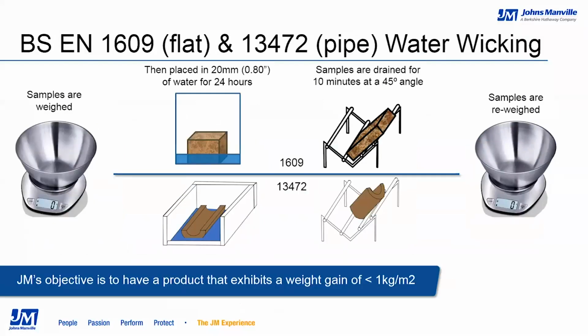The BSEN 1609 and 13472, these water wicking or partial submersion tests really aren't vastly different. The flat material or the pipe are weighed, then subjected to standing water for 24 hours, allowed to drain, and then reweighed. Unlike the vapor exposure tests, these partial submersion tests don't require a preconditioning to remove all internal moisture. They're just conditioned at standard conditions prior to testing. And that's because the expectation is that the inherent moisture in the product will be negligible compared to the liquid